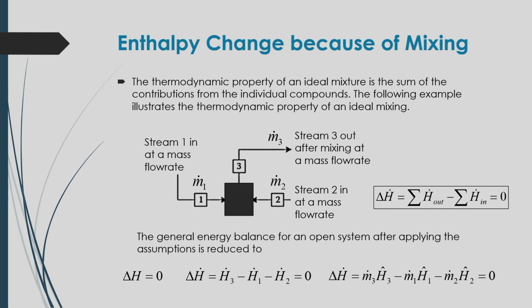Sometimes, if there is no reaction, only physical operations will be there. In the inlet streams, whatever components are there, after a physical operation there may be some unwanted or unused components also in the outlet streams. So, there will be a mixture of several components in the inlet and outlet streams. In that case, this is how the enthalpy change will be there based on the different mixing in different streams.